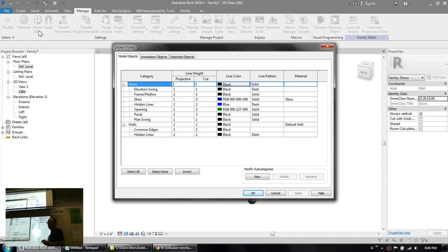And typically when we model the glass that we use in a door, we'll make the two lines about an inch apart. Now what's going to happen is that glass, when you see it in plan, those two lines that are an inch apart can end up reading like one heavy line, and like really heavy, like a 1 millimeter wide line in your plan. That's not so good.